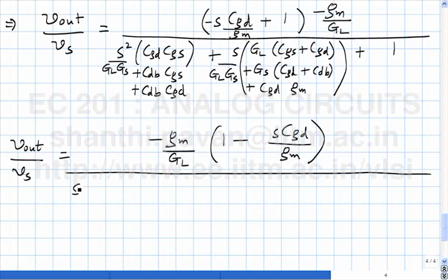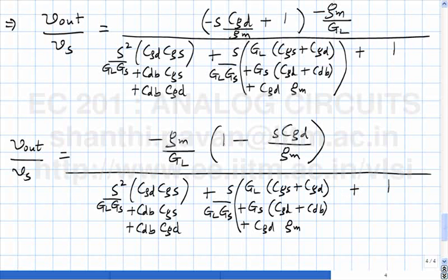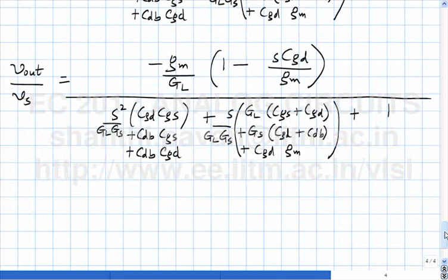So what is the order of the system? Second order. The guys who said 3. So is this dimensionally consistent first? Yes. Then what other sanity checks can you make? At DC, what did you expect?